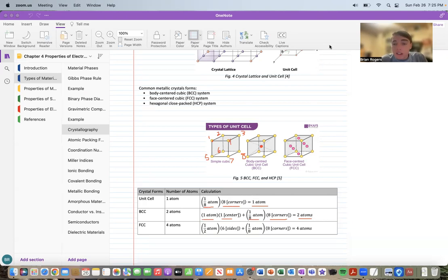And then the face-centered cubic unit cell, you're going to notice that it can store up to 4 atoms inside of it. And so what we're going to see here is that at the face, remember on the face, what we're going to notice, let me try doing this 3D representation, might help a little more. And so half of the atom is going to be on this face, where the other half of the atom will be on the other face. Because if you think about the diagram up here,